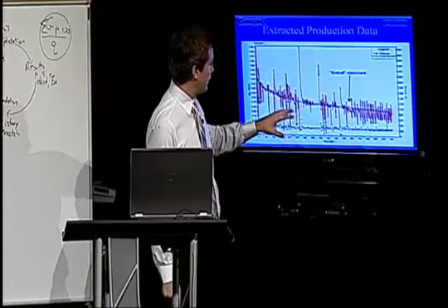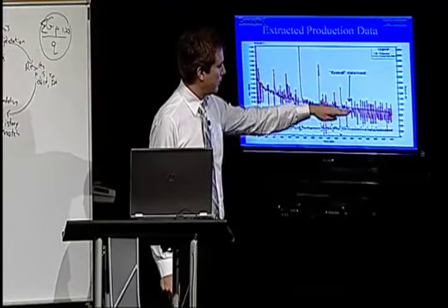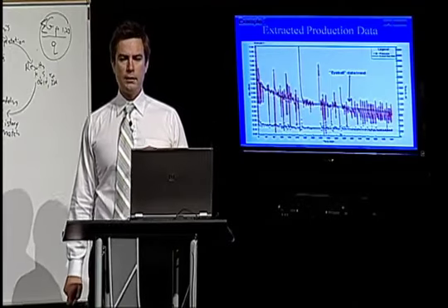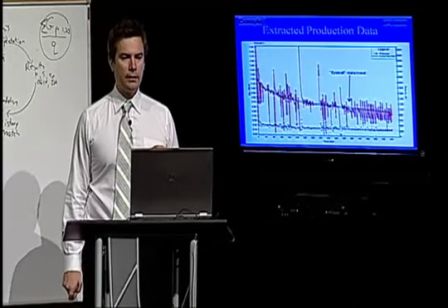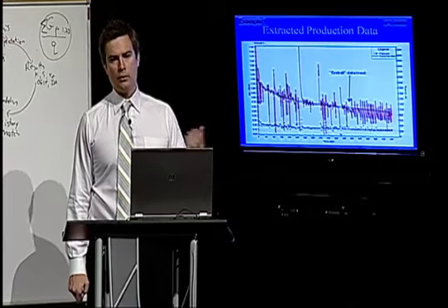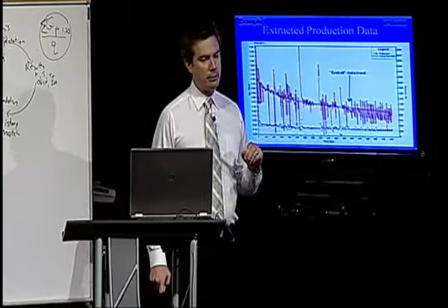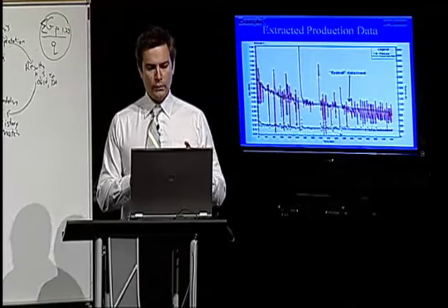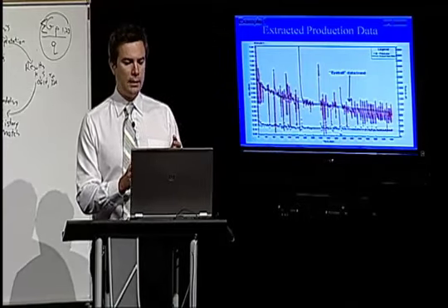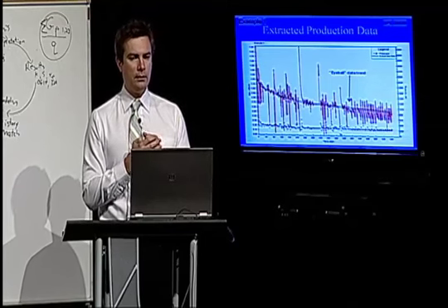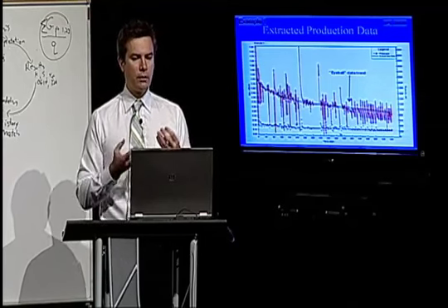The other way to do this is to go through and pick out all the data points that have fallen below critical liquid lift velocity, and there's an easy way to calculate that velocity using the Turner or the Coleman correlation. And once we've done that, we can eliminate those data points. Both of those methods involve filtering the data, and I used the term earlier on reservoir signal extraction. Both of those involve a reservoir signal extraction.